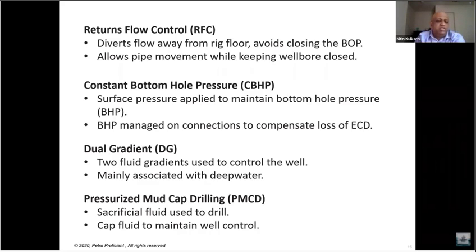It's important to know all these terms, because sometimes a company would decide that we just want to use MPD for return flow control. We are not going to do any pressure management. So in that case, you would still have an MPD system set up on the rig, and you might be wondering, what are we doing? Here the company is only, and I've been on such jobs, just monitoring the returns from the well, and we are not doing any pressure management. But that is what the objective is for this particular job.